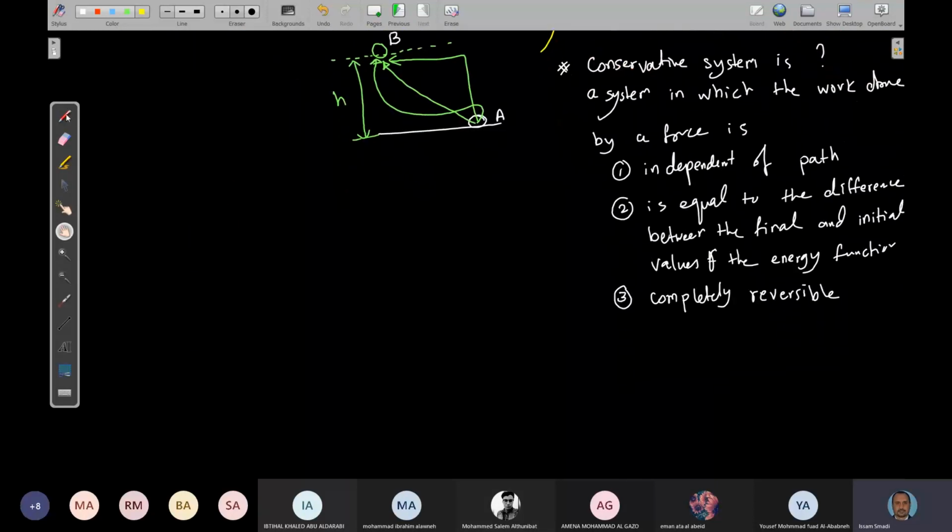So now let's try to find the integration. So I will start with V1. V1 is equal to R1 I1 plus d by dt of lambda 1, and lambda 1 can be written as L1 I1 plus the mutual inductance multiplied by the second current, which is I2.